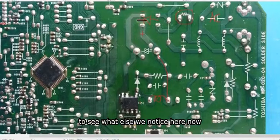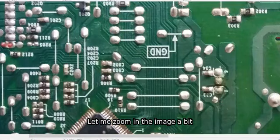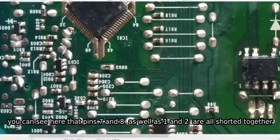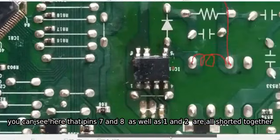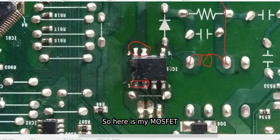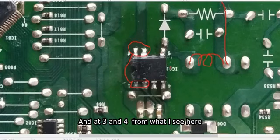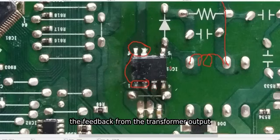To see what else we notice here now, let me zoom in the image a bit. You can see here that pins 7 and 8, as well as 1 and 2, are all shorted together. So here is my MOSFET. One leg of the MOSFET is here. The other leg of the MOSFET is at 1, 2, 7, 8, and 5. And at 3 and 4, from what I see here, it goes to the coupler to take the feedback from the transformer output.